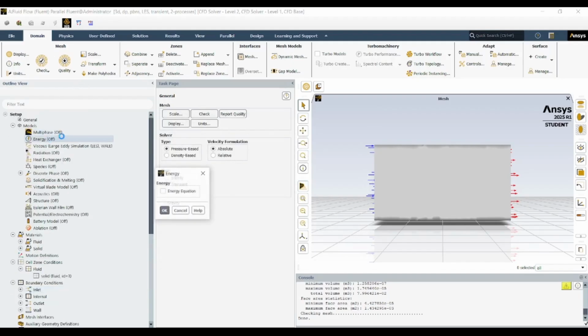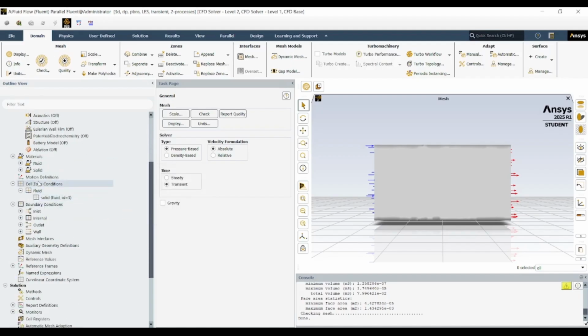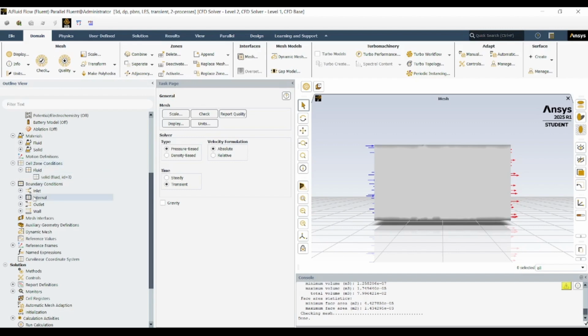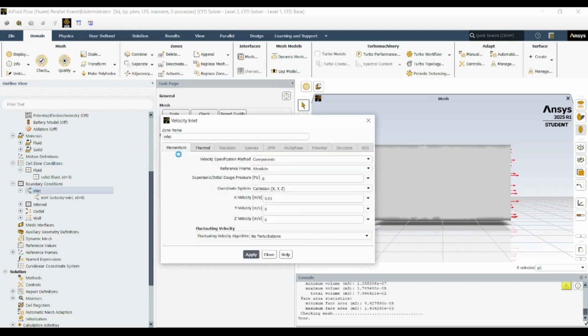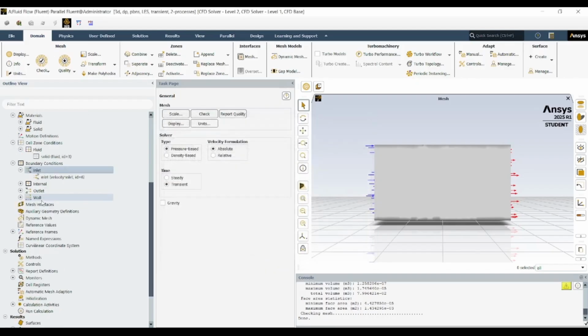The velocity field clearly shows how the fluid slows down at the front stagnation point, accelerates over the curved sides, and drops sharply in the wake region behind the cylinder. The contours often have blue zones at the front, low velocity, and bright red streaks at the sides, high velocity, where the flow is fastest.